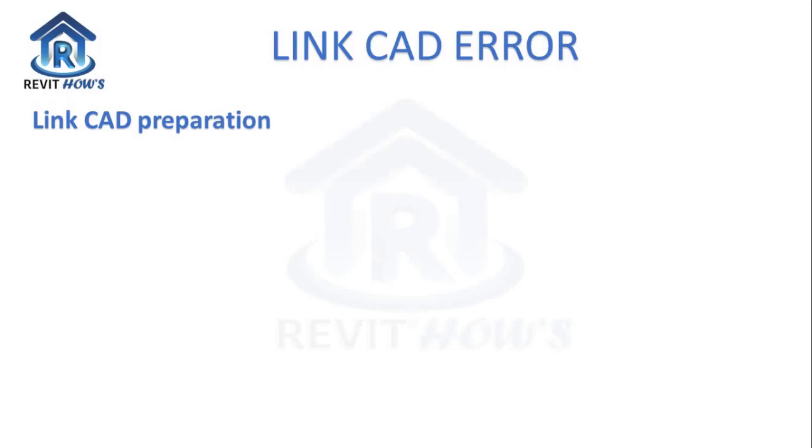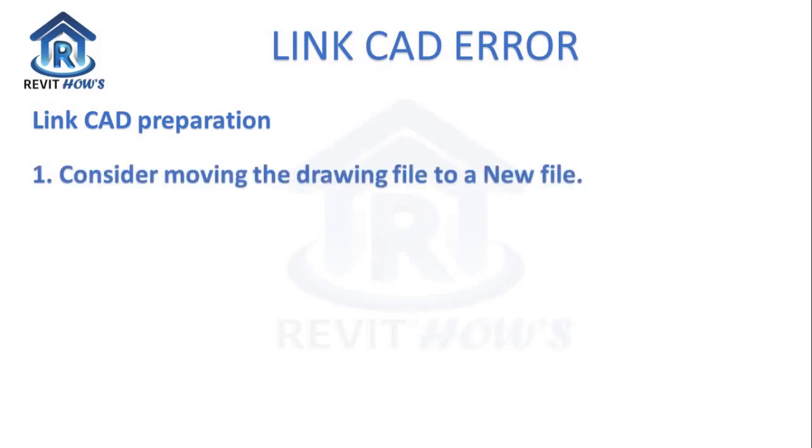Depending on the condition, beforehand, I consider moving the drawing to a new drawing file. This will save you a lot of time, and it will give you more confidence in the file you are about to insert in Revit, since you can remove the elements you don't need and leave the ones that are needed for the particular link CAD file.